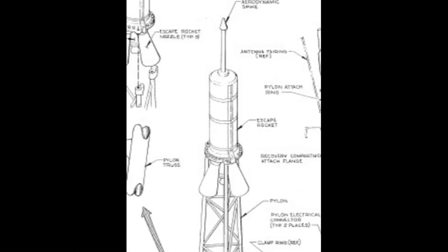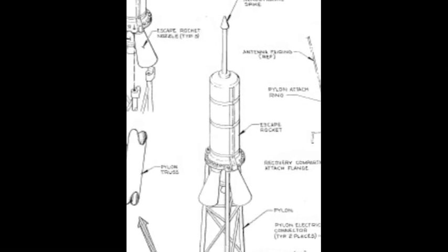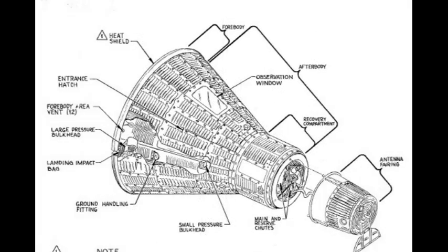2.3. Forebody. The capsule forebody, Figure 2.1, mainly consists of a large, blunt, dish-shaped structure that is supported by the large pressure bulkhead and adjoins the afterbody conical section. The large pressure bulkhead internally separates the forebody from the afterbody. The forebody dish-shaped structure is a heat shield that is designed to protect the capsule from extreme thermal conditions during orbital and re-entry flight. It is also designed to prevent capsule damage upon landing impact.